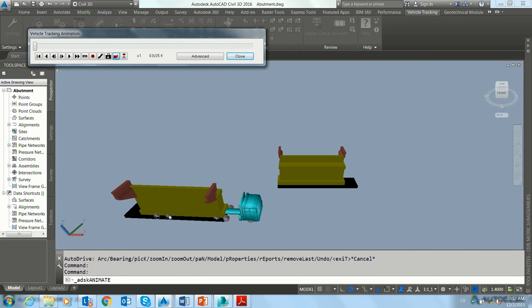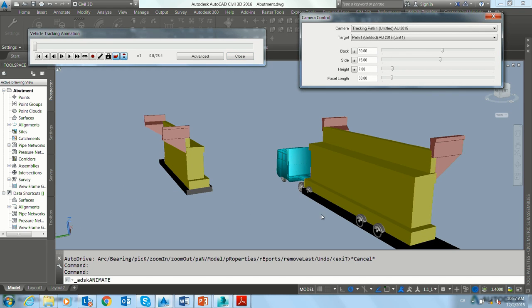Yeah. And I didn't specify this elevation properly. What I did was a stupid thing: I was mixing millimeters and meters. I put 0.9 as meters, but it should be minus 900 millimeters when I was creating this block. Because right now it's in fact sitting on the ground, and I don't have this tire width. So I was talking about this, but I didn't consider the change of units, yeah?